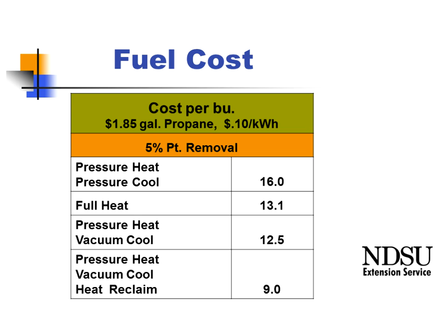So even though this one is going to be the most economical from a drying cost standpoint, my experience at least, we don't see very many of these actually being used. They will reduce the drying capacity just a little bit, and we see most of the systems either being full heat or pressure heat with vacuum cool.